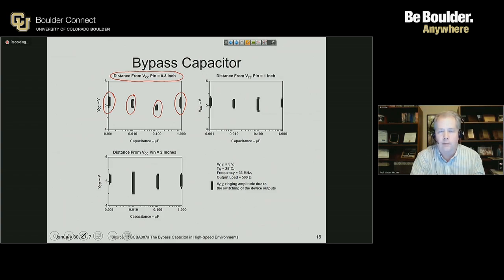The other thing that can influence what I read with a scope probe is resonance effects. So if I have chosen capacitors that have a particular capacitance, inductance, resistance, and they interact with a circuit in a certain way, you can get results which will show you maybe greater noise than what you were hoping for.